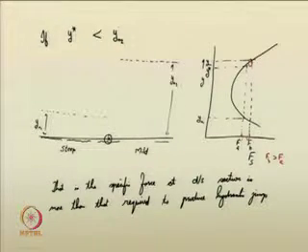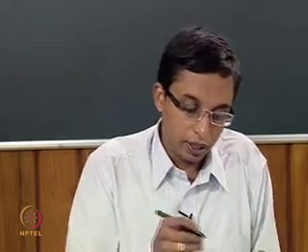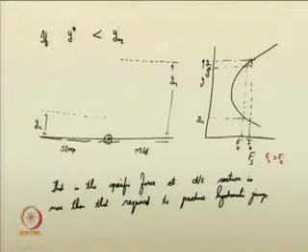So, the flow adjusts in such a way that the hydraulic jump is now pushed to the upstream location, and the jump is formed in the upstream location here, followed by an S1 curve. Then it joins the normal depth of the downstream. That is the process. So, I can just draw it here.